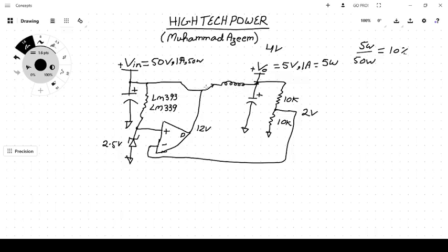And another advantage of using an inductor is that it consists of copper wire, and we know there is almost no DC resistance of the copper wire, so there would be no dissipation inside the inductor. So we have solved the dissipation issue as well, but now another problem occurred.